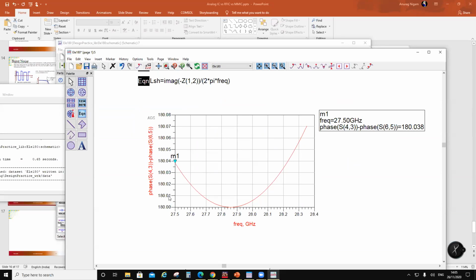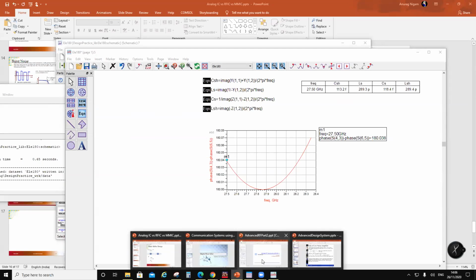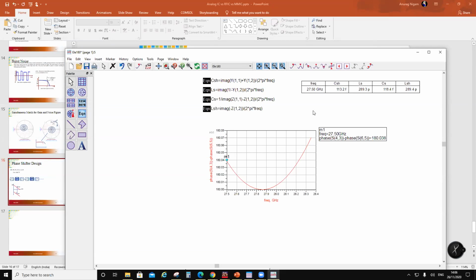You see? It is 180 degrees broadband. It's like an error of 0.01 or 0.02. How does it matter? Across the band, you have no issue. It is a flat 180 degrees. Versus if you were to do a 180 degree element delay on one side, then you will have this slanting like that. Right now, what you have done is a broadband 180 degrees delay on all the frequencies.